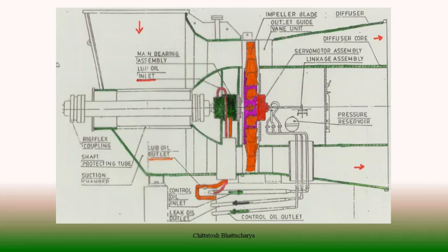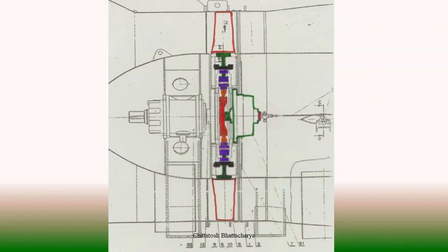This kind of fan is specially accommodated within the diffuser with a hydraulic servo motor fitted with a control oil supply arrangement, and with this control oil supply they can tilt the individual blades in unison, which are coupled together, and that way we can regulate the gaseous fluid flow.